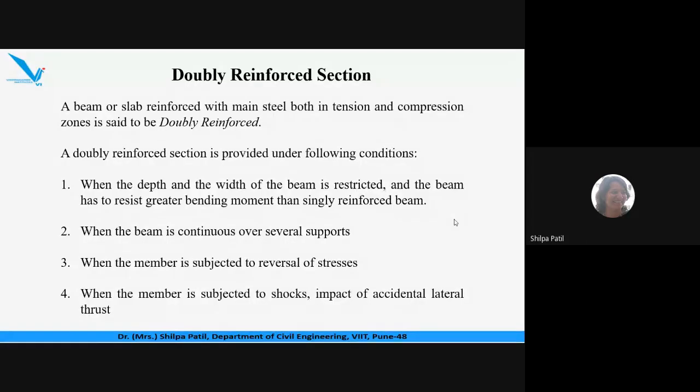If you recall the analysis of continuous beams, suppose we consider an example of a continuous beam with two spans. Two spans means there are three supports. ABC is the beam, with supports at A, B, and C, everywhere a simple support. So the beam is continuous over support B. If you recall the bending moment diagram for this beam, at the support B also we get a certain bending moment, and that normally comes as a sagging bending moment. Am I right?